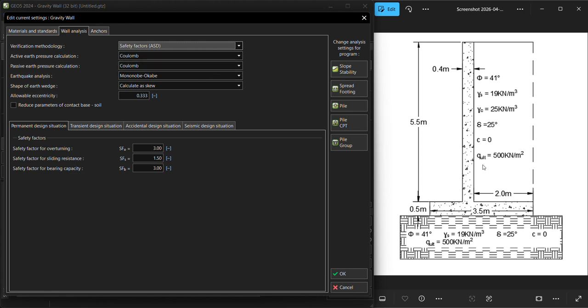Now let's come back to our question. So we have two types of earth pressure calculation, which are the Rankine and the Coulomb's. But with Rankine's theory, it states that before you can use it, you have to satisfy certain conditions. The first condition is that the wall supporting the soil must be vertically upright, which, as per the drawing, our question has passed. And also the cohesion between the wall and the soil must be 0, which in our question has also passed. And the third one is that the soil being supported must be dry, which we can assume is so, since our cohesion is also 0.